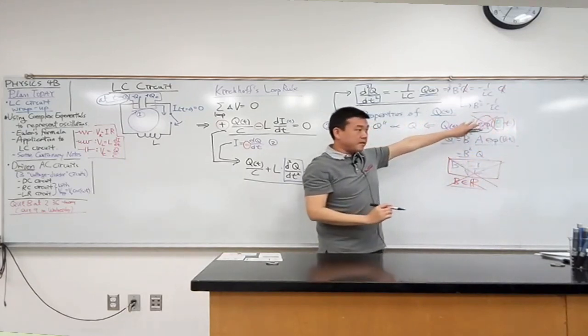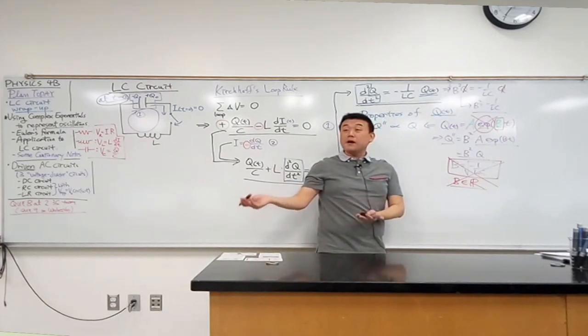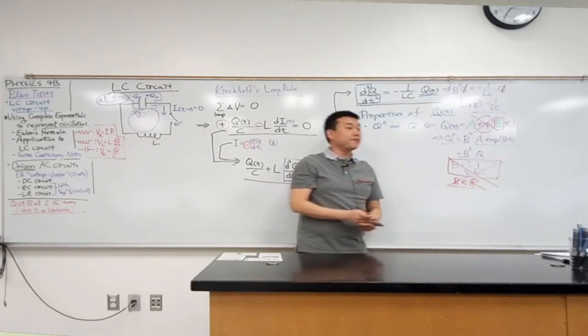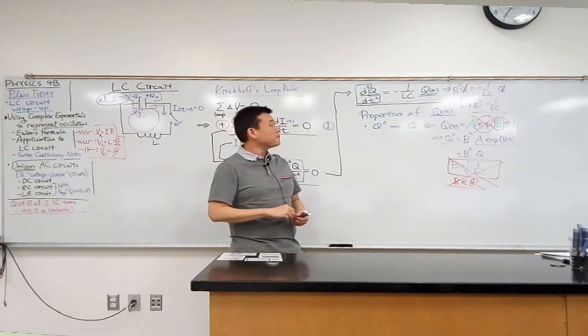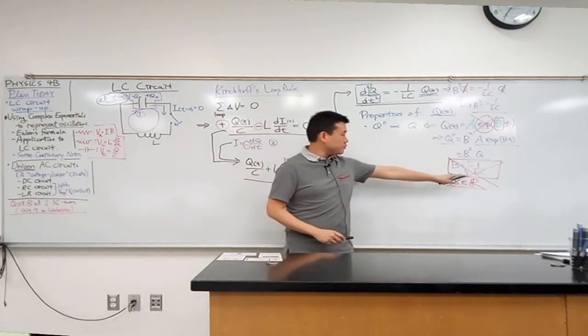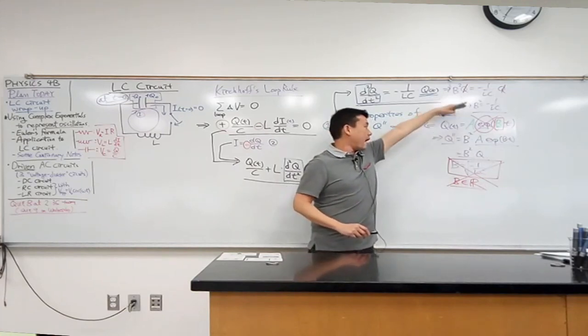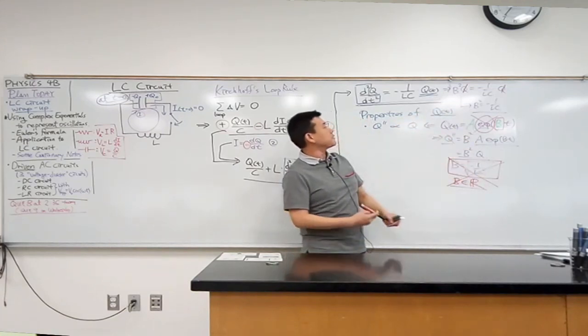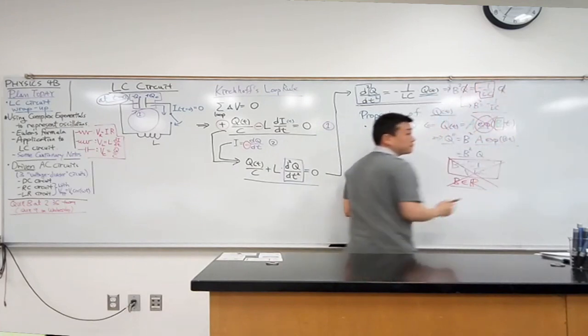We're going to revisit this, and complex exponential will actually become one of the best guesses for many different circuits in a little bit. But for now, because we are limiting ourselves to B being within the real numbers, all this line of reasoning gets stopped by the fact that this coefficient here is negative.